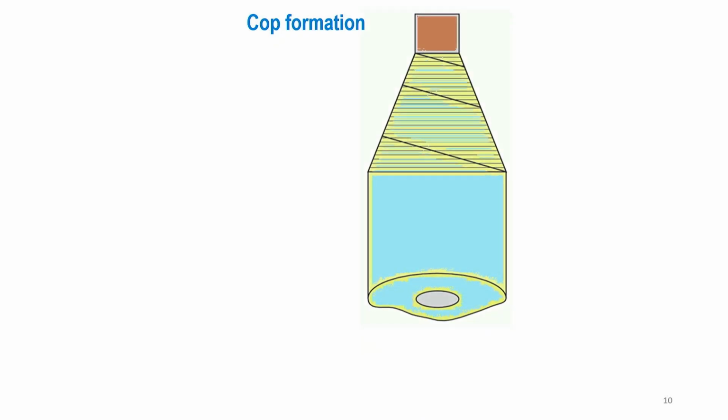Now, you can see during the upward motion, when the ring rail is moving slowly, the majority of the yarns are almost parallel. They are wound during this, which is called the winding layer. And while coming down, shown in black color, the angle of wind will be larger.